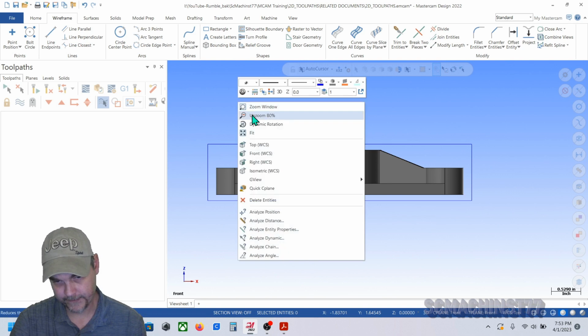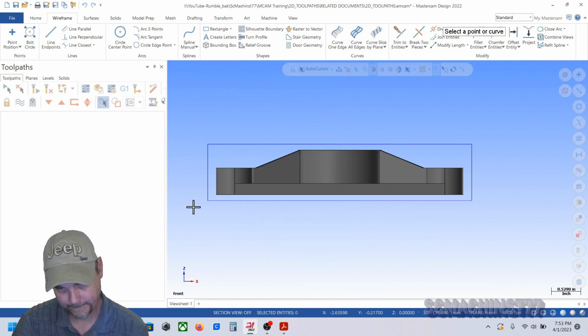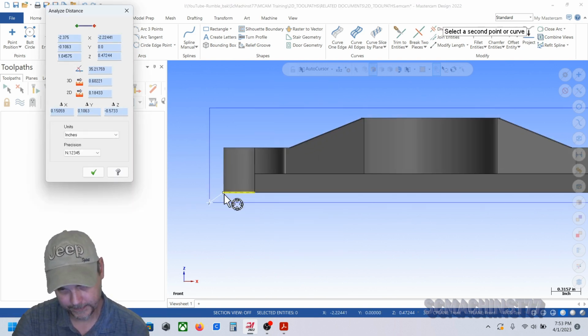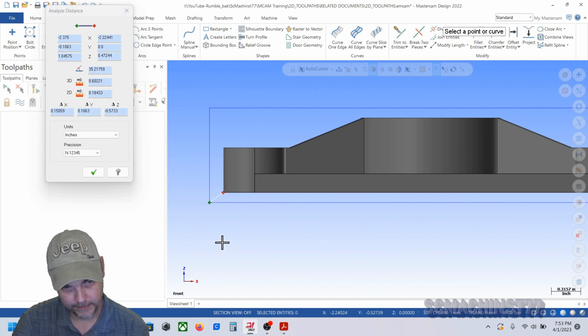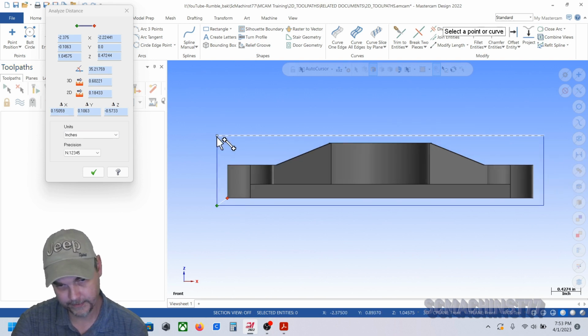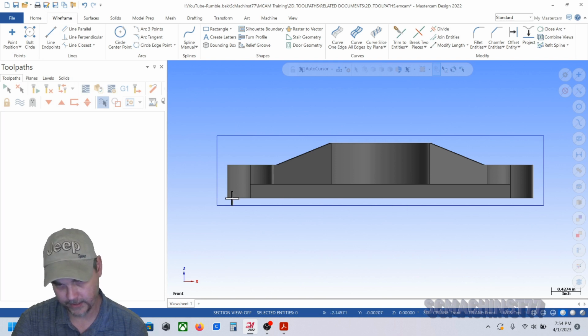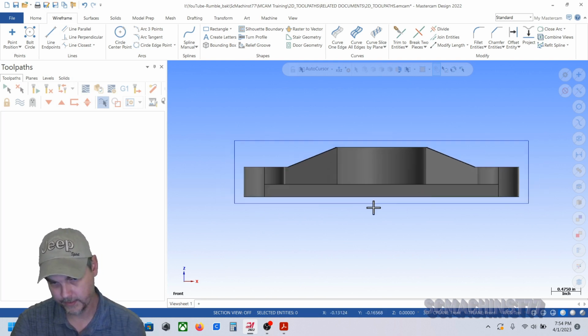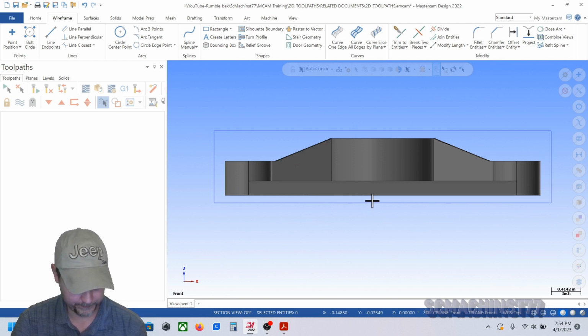As far as our faces go, we've got about 100 thousandths or 3 millimeters on this face, and should be about the same here. Okay, so we will take some off of that face, because I don't want to leave 100 thousandths on there, that'll put too much stress in it.